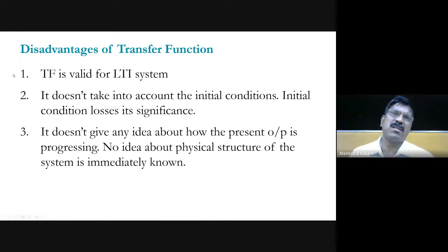Okay, now what are the disadvantages of transfer function? The first one is that, as per the definition of transfer function, it is valid for an LTI system, that is, a linear time invariant system. It is not applicable for a linear time varying system, or a nonlinear time invariant system, or a nonlinear time varying system, and so on. So this definition is applicable only for an LTI system, that is, a linear time invariant system.